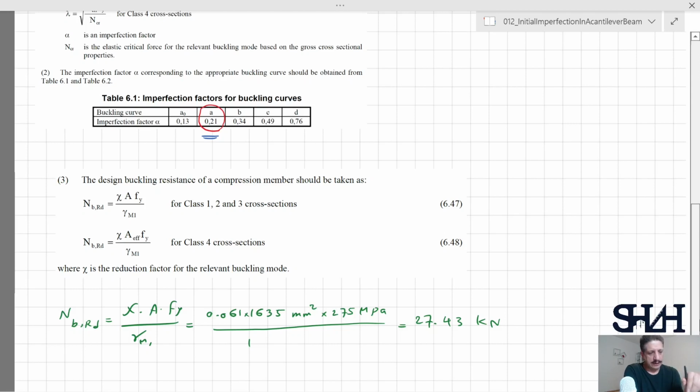So here is how the amplification factor would affect the buckling or the maximum capacity of a column, and the curves in Eurocode are produced by the same concept. For example, in Eurocode 5 for timber structures, we will see directly this amplification factor effect in one of the terms, if I recall it correctly.